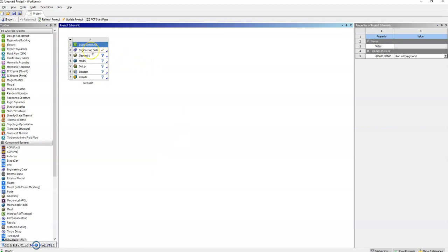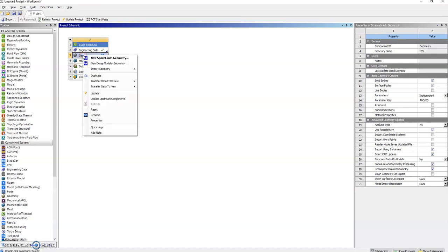Having defined the material, it's now time to obtain a part. Different options there. So open the geometry cell here, and if you right click on it, you see that the main options are either import geometry, and sometimes it's smart enough to see if you have got some CAD type file. This one is totally different, so it's not relevant here, but otherwise there are two embedded CAD software in ANSYS. So the first one is SpaceClaim.